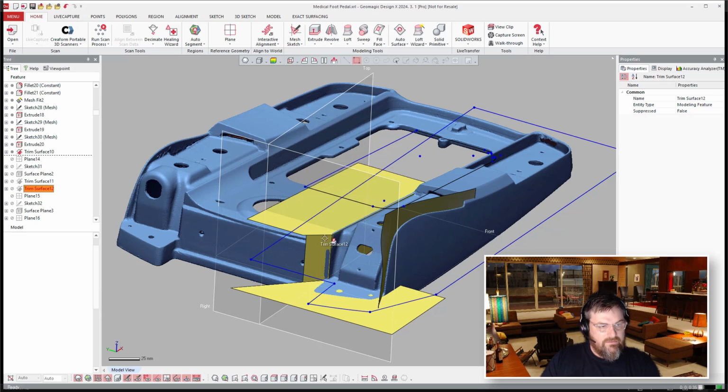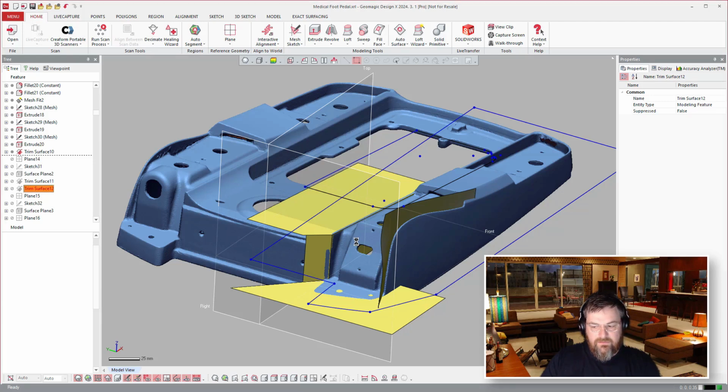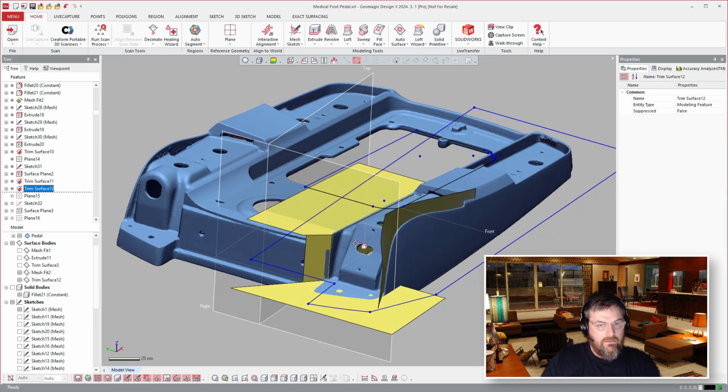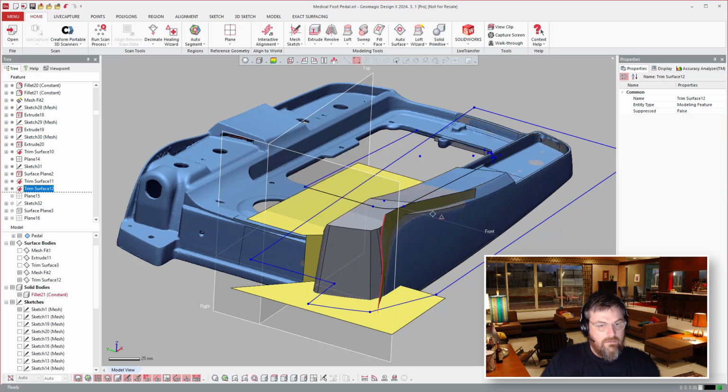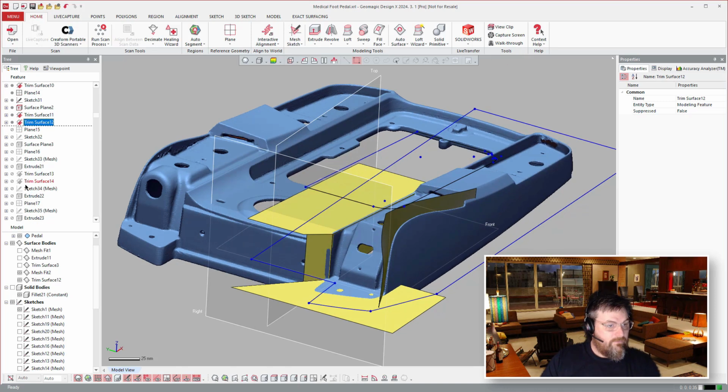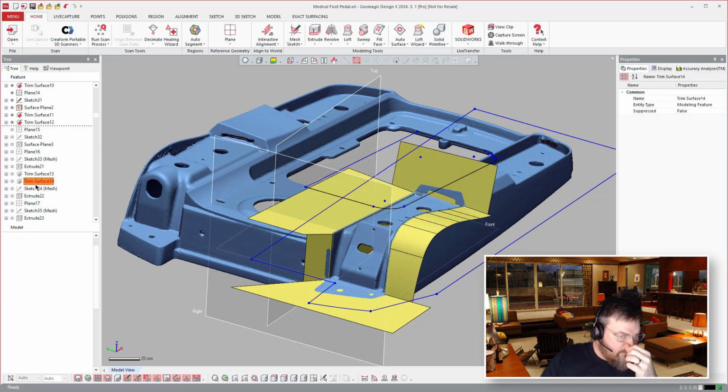And then I'll turn the solid on here in a second, just to refresh where the solid is versus where the mesh is, so you can see the approach here. So if I turn that solid on, you see here, it looks like we're going to cut this all away in one stage. So now we'll come forward a few more fits and extruded surfaces and a few more trims.